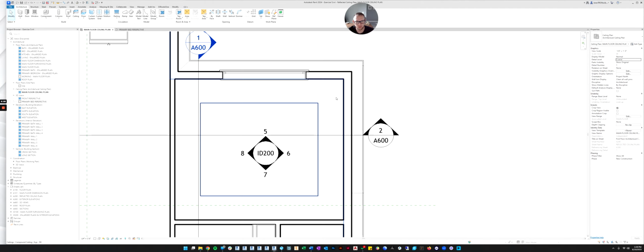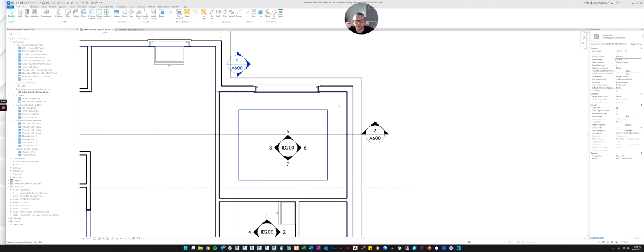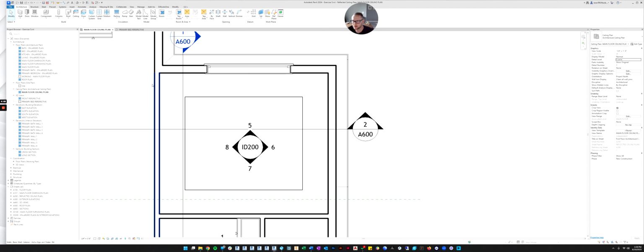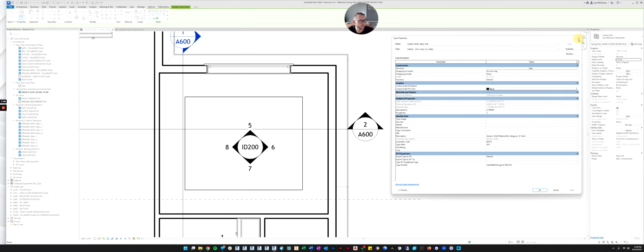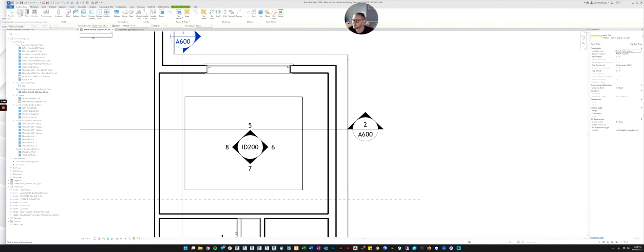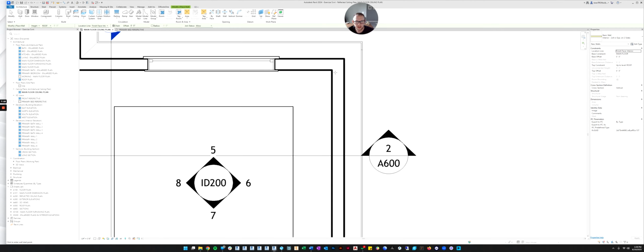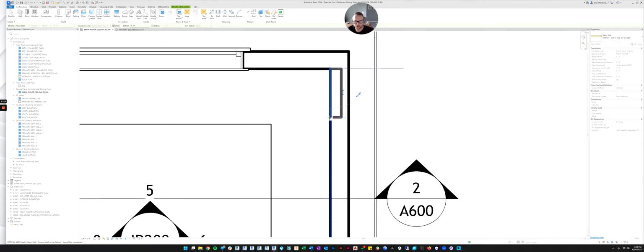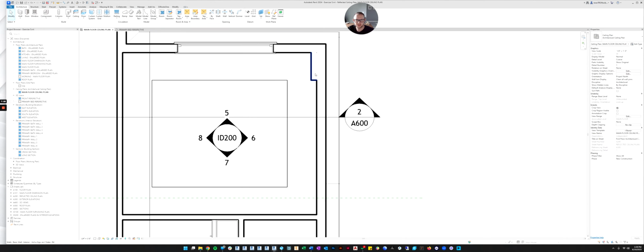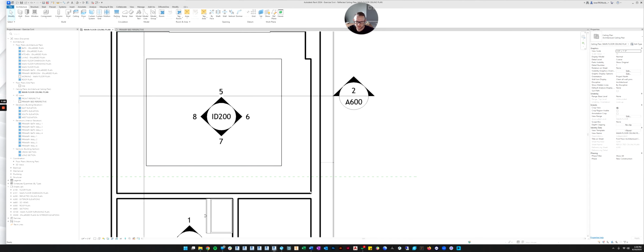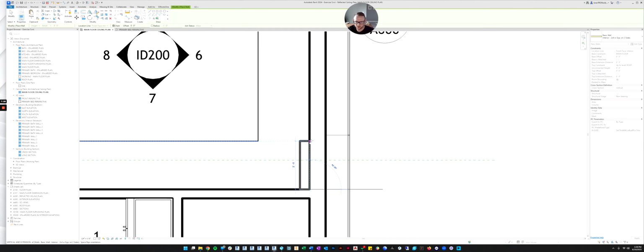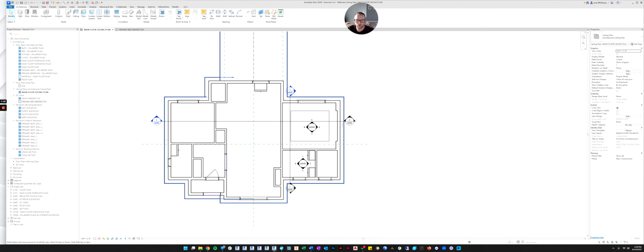Another design element you might want to make is little bump outs on the wall. So let's do that. Let's go to the wall command. Go to the architectural wall command, and let's do our 2x4 wall. Let's just draw 2 walls right against each other. And let's have it come out 2 feet to match the soffit. And do you see how the walls joined?